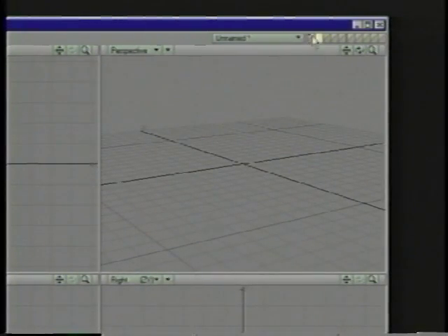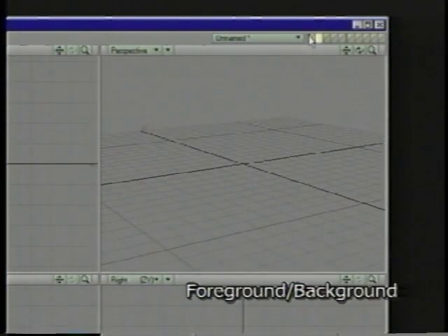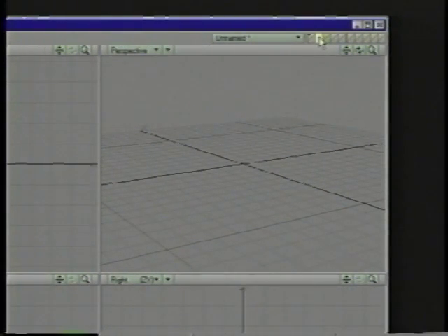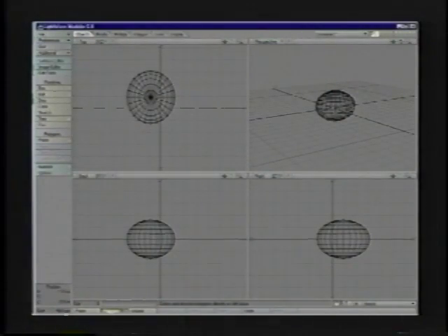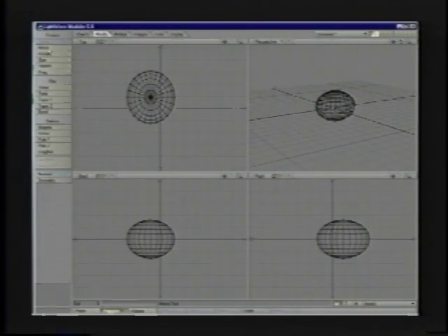And if you notice that each tab is kind of separated by a little diagonal line, that means that each tab is split up into foreground and background. So if I select layer 2 as my current layer, and then I select the bottom of layer 1 where I put the ball, then you'll see that show up as black. And that means it's a background layer. And whatever I try to do, if I try to move it or what have you, I can't do it. So if I say modify move, it won't go because it's a background layer, and it basically means it's inert.